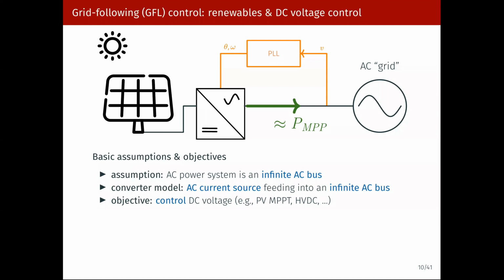So if you look at that space, you cannot emulate the fault response of a synchronous machine with a power converter without oversizing it dramatically. So this is a hardware limitation, and this comes from the fact that the semiconductor switches in the power converter have typically overcurrent capabilities in the range of maybe 20–40%, whereas a machine can go 3 times over its rated current for 100 milliseconds or so.